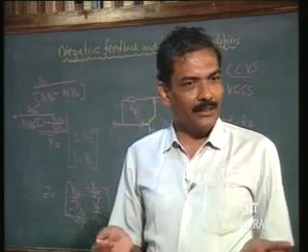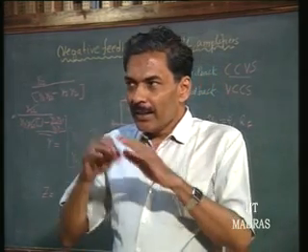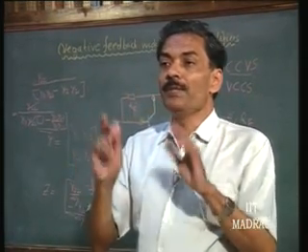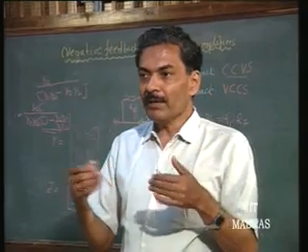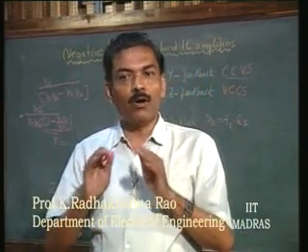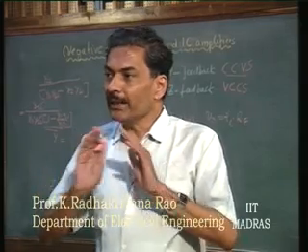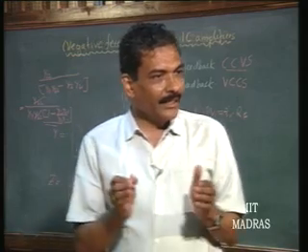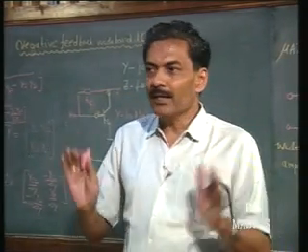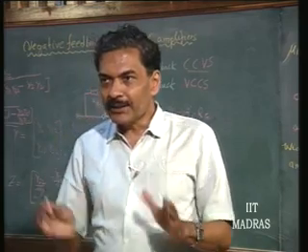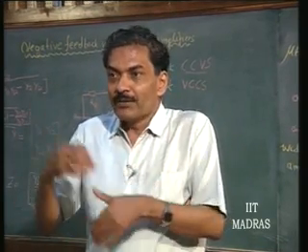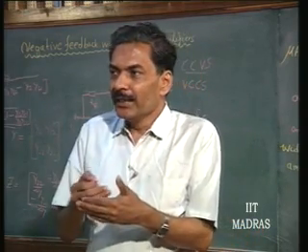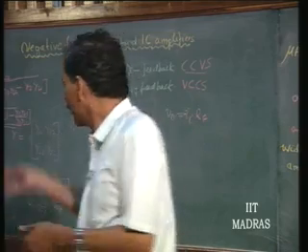In terms of any parameter, you can say that the parameter is getting modified by a factor of 1 minus P12 P21 divided by P11 into P22, where P is called the immittance matrix, immaterial what the parameter is, okay. 1 minus loop gain is defined in terms of the immittance matrix. This is generalized; it is this loop gain which is going to modify all the factors. If the gain is getting reduced, it will also get reduced by the same factor, that let us see.